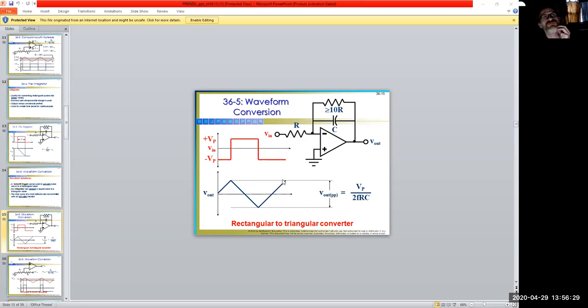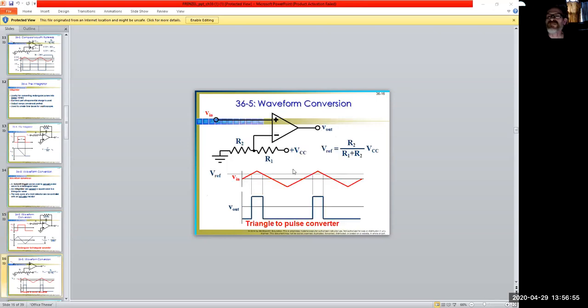We do have a nice time base to this thing that's allowed, and I wish we could do, well, we can't do that with the simulator. But I wish we could do even a comparison, setting up similar RC time constant circuits, where you could compare a passive filter to an active filter and see what your overall output response would be by comparison ratios. And I guarantee that what you get with the op amp filter compared to the passive style is a much, much cleaner, much faster, smoother signal, without the noise, without the distortion and that type of thing.